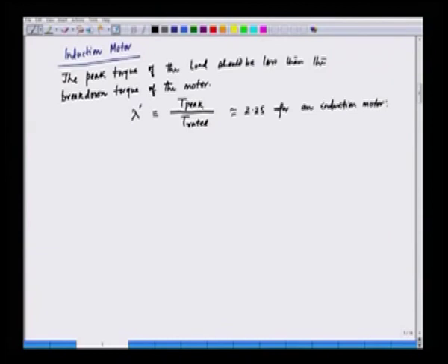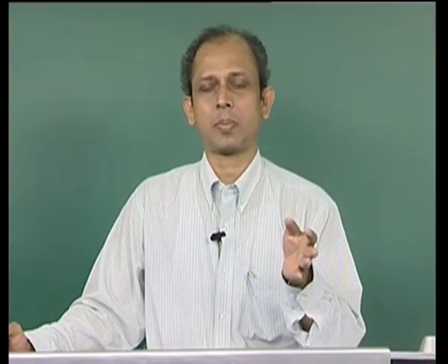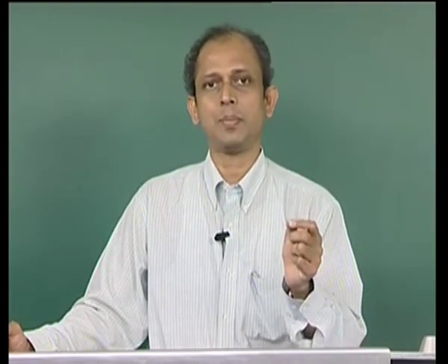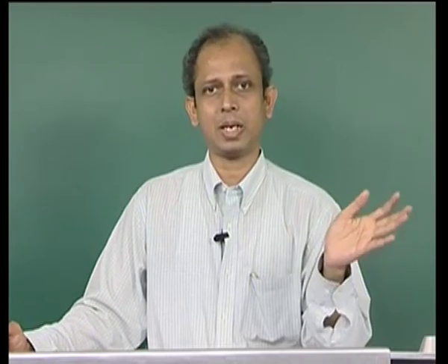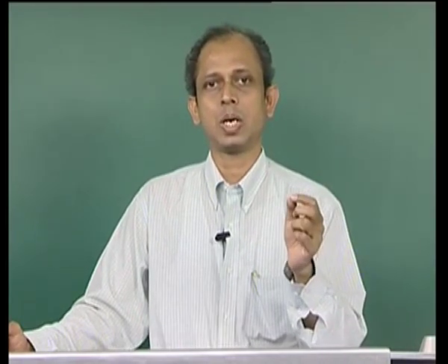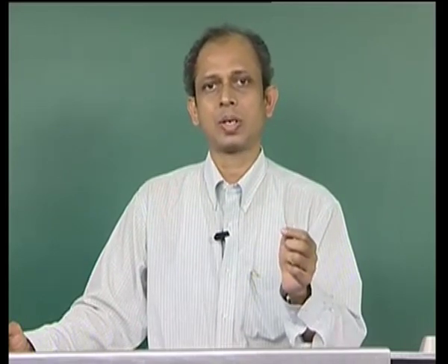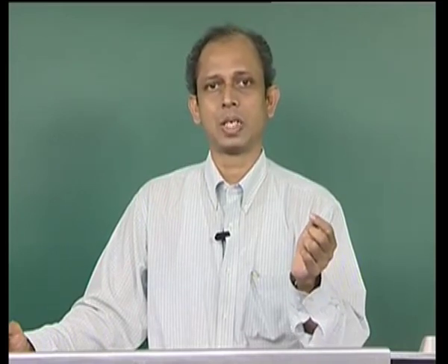So, we know that we have already found out the equivalent current, I equivalent, and we know that approximately we can say that the current and torque are proportional. So, we can also find out T equivalent. So, what we do usually, based on the T equivalent that we have calculated earlier, we choose the rated torque. So, the rated torque is the next available torque higher than the equivalent torque that we have obtained.